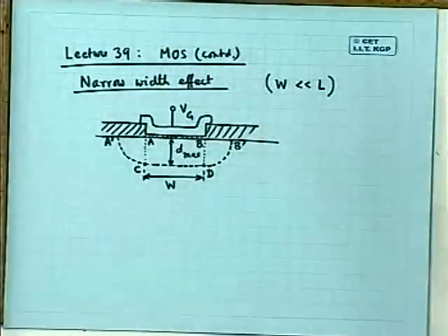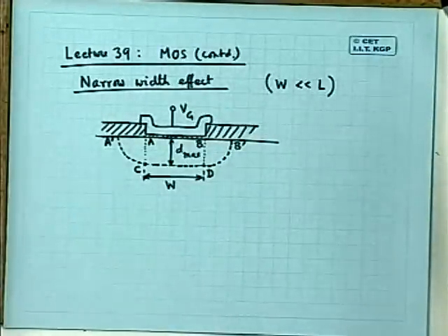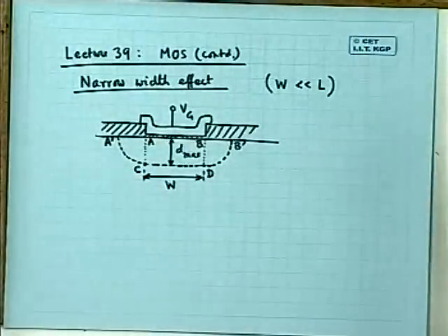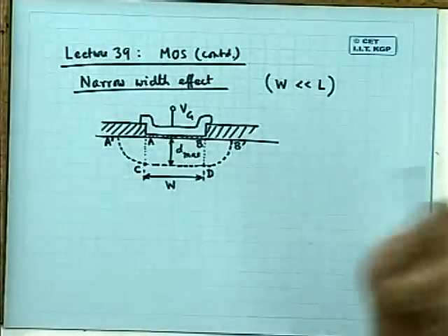So the inversion layer, which is naturally formed in the absence of gate bias, will not be confined only below the channel, but also everywhere. So what will happen as a result? All the devices will be connected by the inversion layer. All the MOSFETs, which should otherwise be electrically isolated, will be connected via the inversion layer. And your circuit will not work.